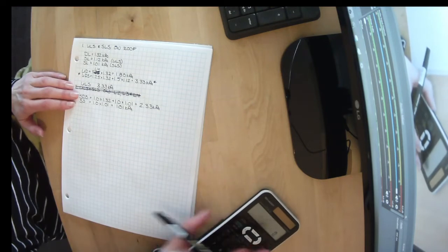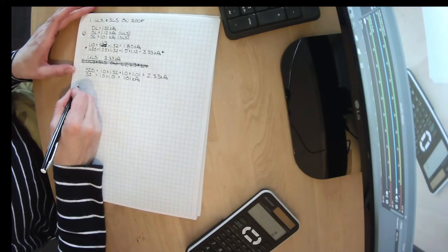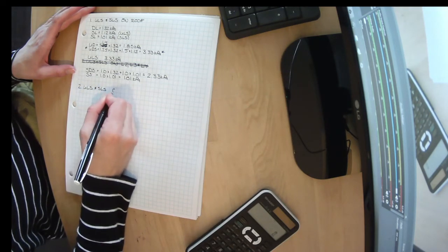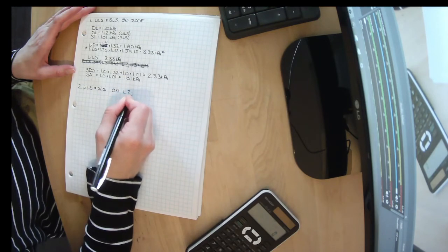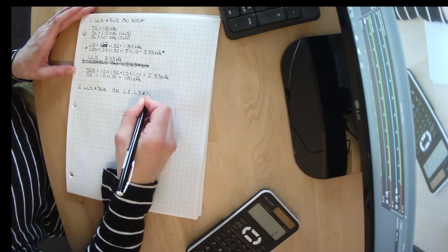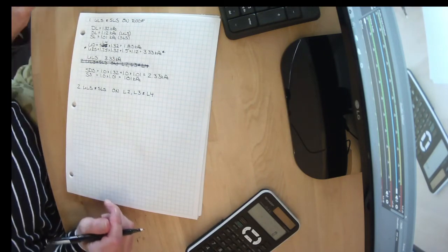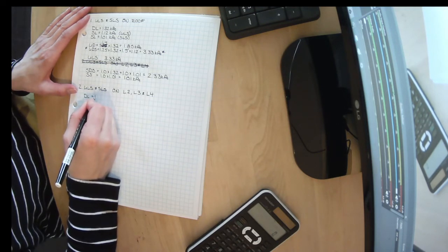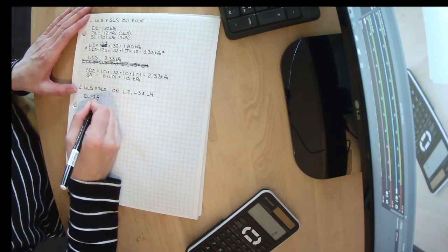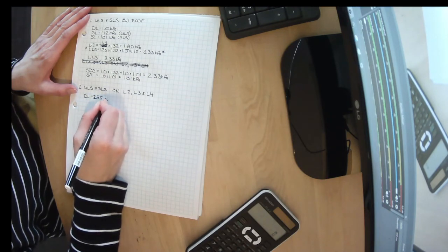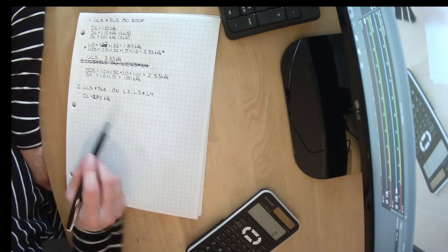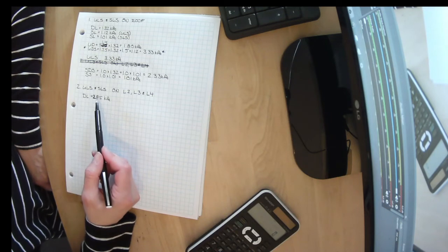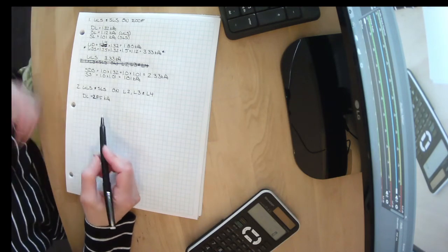This isn't a matter of finding the worst case one. Step 2, ultimate limit states and serviceability limit states on level 2, level 3, and level 4, I believe, are how many floors we have on this. And last week, we calculated the dead loads as 2.85 kPa. We looked at what the flooring assembly was, and we broke it down item by item and looked up what the weight of all of those items were and determined that the appropriate design dead load for these floors is 2.85 kPa.